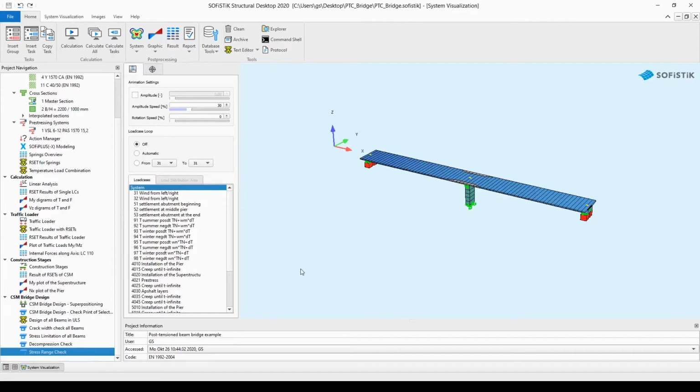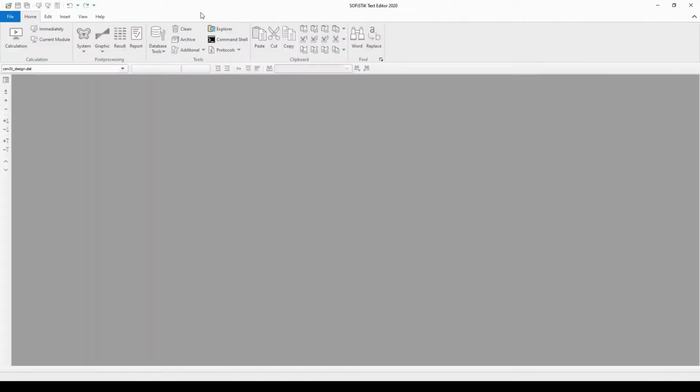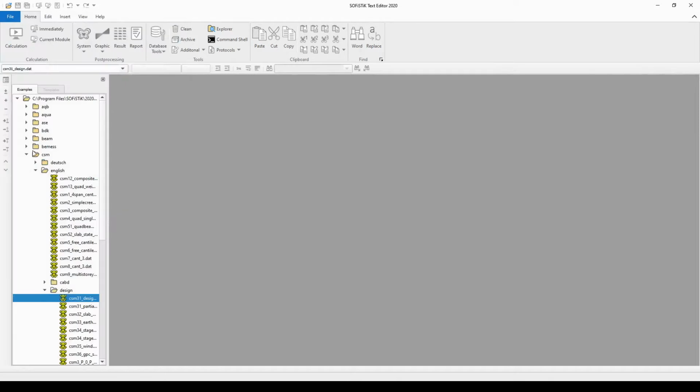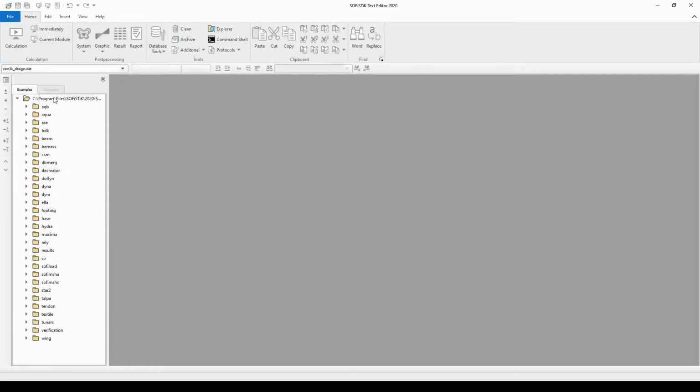In this video, I would like to introduce to you a new fatigue check approach, namely the damage equivalent stress range check for load model LM3. The best way I can do that is with the help of a text-based input with TEDdy. So I would like you to open TEDdy 2020 and then go to the File menu and choose the examples. If you do so, the example folder will be opened for you, and here you need to open up the